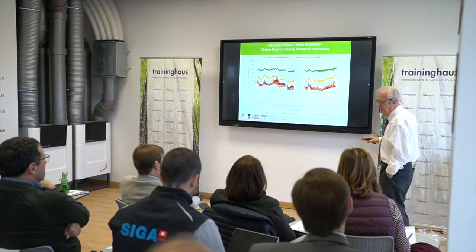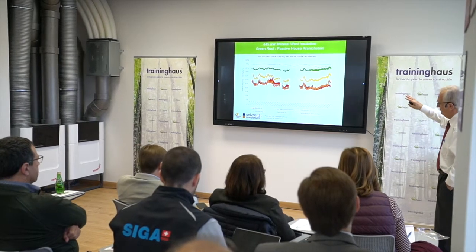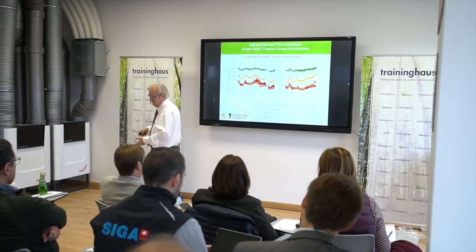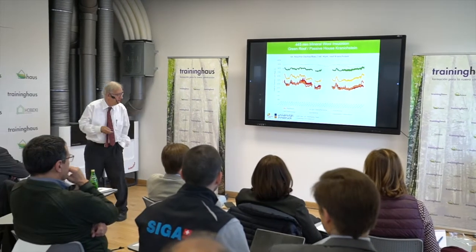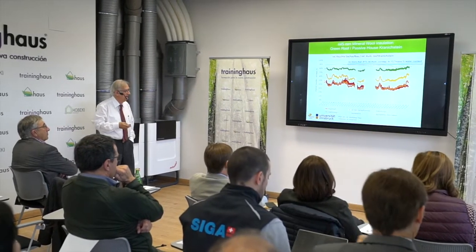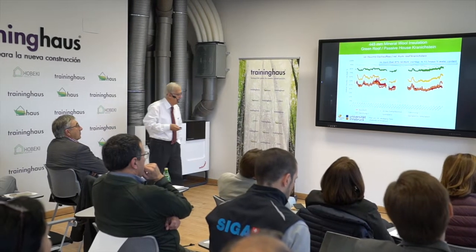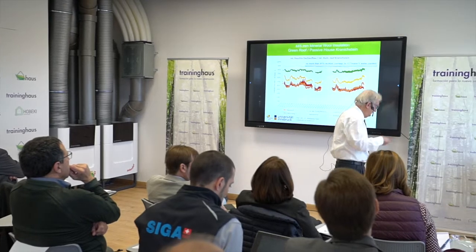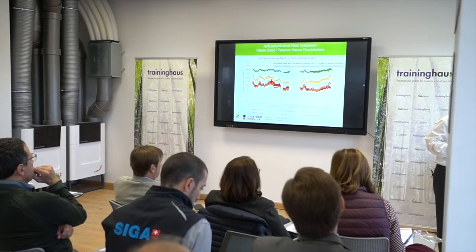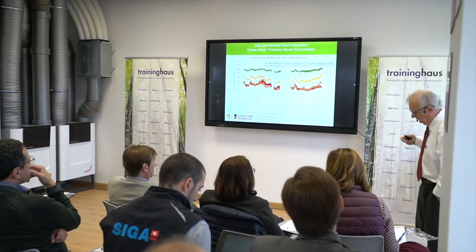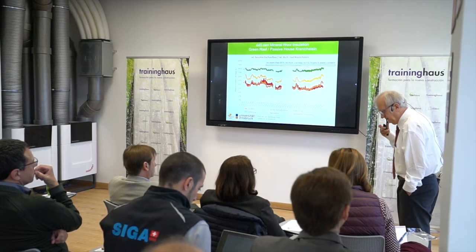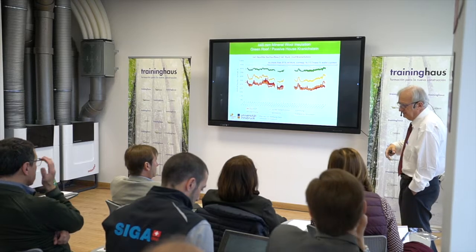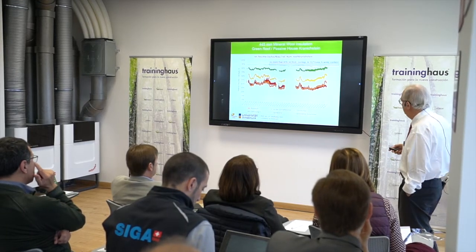And that's all still fine. We are still in a range where this is also normal. Even in a ventilated roof, you won't be lower because that's what you normally have on the outside. You have this average of about 90%. So yes, it looks like it's working. No more than 91% of relative humidity, and this is corresponding to about 14% mass percentage of humidity in the timber material, which is okay for timber material. You could go up to 17, 18 without any problem.